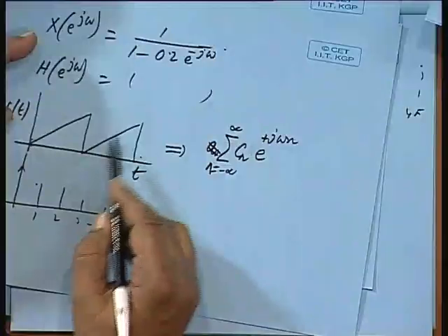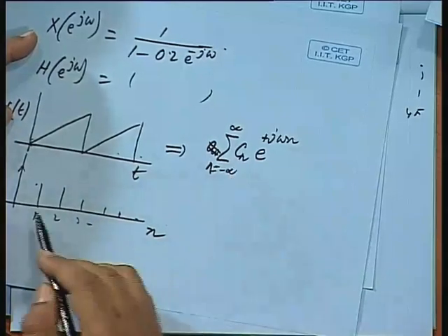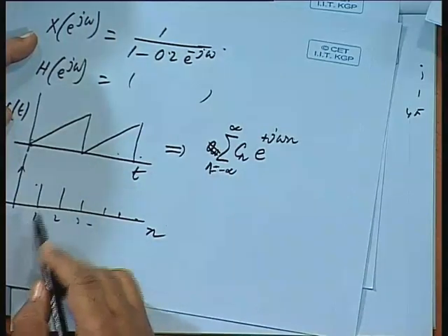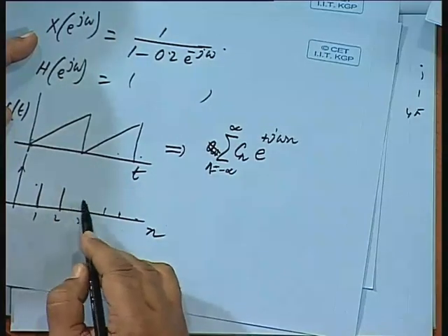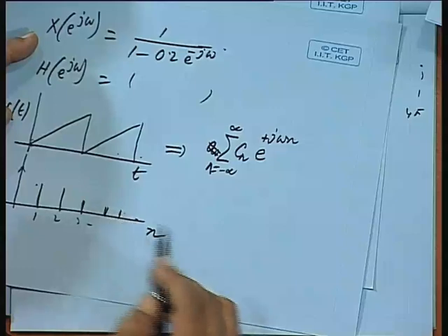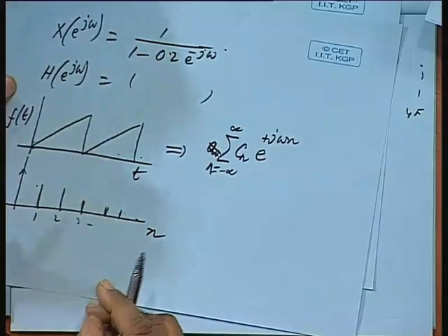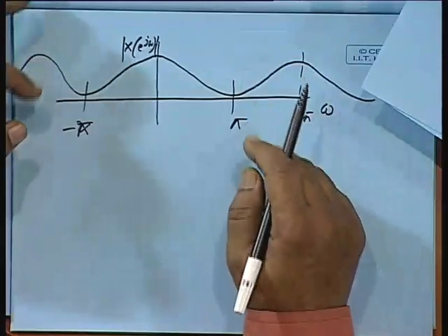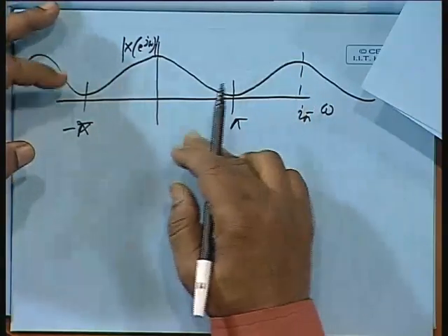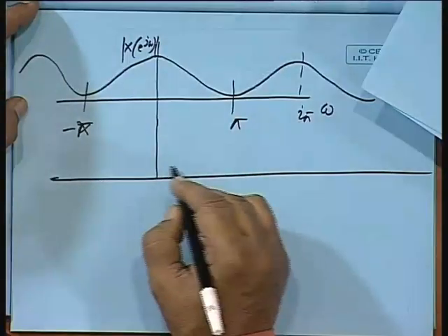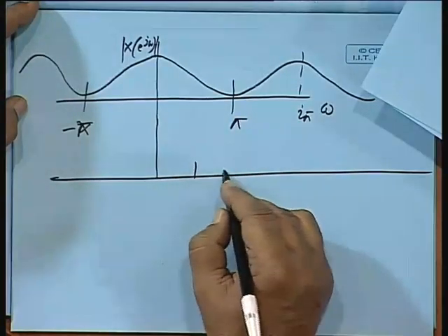In the time domain, if it is a periodic function, then in the frequency domain it is discrete lines, is it not? So, you just stretch your imagination. In the frequency domain, if it is periodic, then what is it in the time domain? It will be lines, and precisely that is what we have started with. It was x[n], is it not?